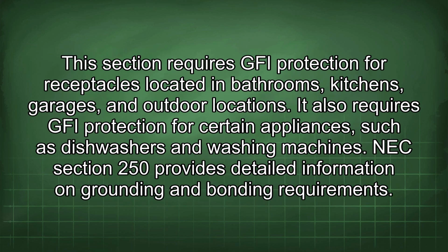This section requires GFI protection for receptacles located in bathrooms, kitchens, garages, and outdoor locations. It also requires GFI protection for certain appliances, such as dishwashers and washing machines.